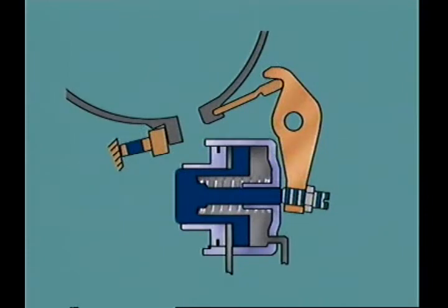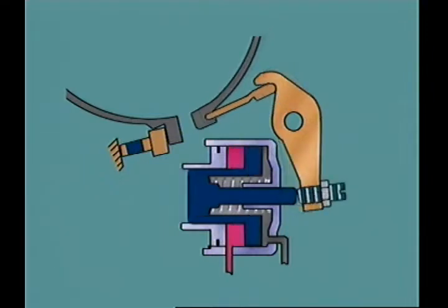Pressure release servos can also have pistons with unequal areas. In this case, the release side has a larger surface area than the apply side. The band is brought into operation by directing fluid onto the reduced area that surrounds the hollow portion, accommodating the return spring.